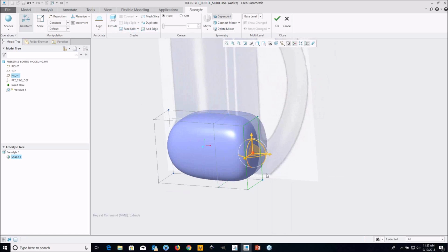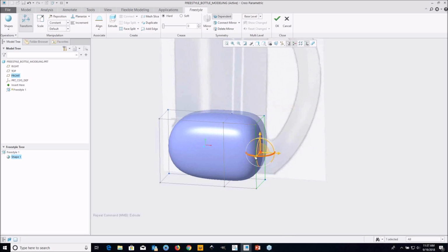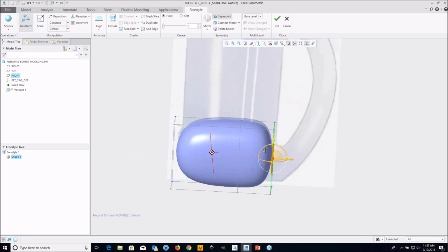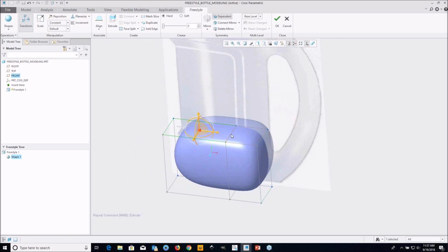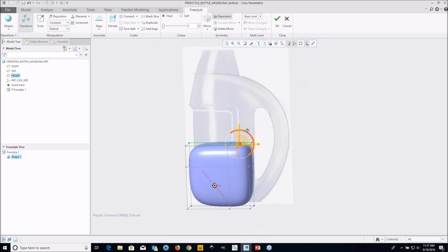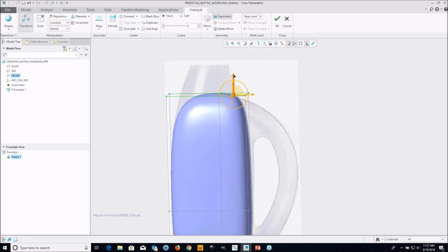So I'll click Extrude, and what that does is that's basically going to add geometry to your model, okay? And then from here, I'm going to select these two top faces as well, and then right-click and Extrude, right? So you can see that in the beginning here, I'm just kind of trying to rough out the shape.